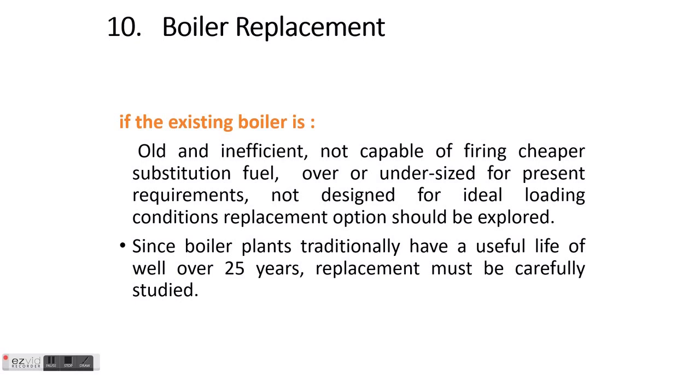10. Boiler replacement. The potential savings from replacing a boiler depend on the anticipated change in overall efficiency. A change in a boiler can be financially attractive if the existing boiler is old and inefficient, not capable of firing cheaper substitution fuel, over or undersized for present requirements, or not designed for ideal loading conditions.